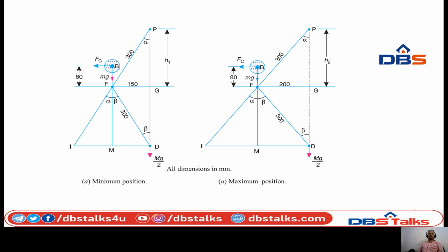Then substitute the values: FM by BM is 0.26 by 0.34, into (10 plus 100) by 10, where small m is the mass of the ball and capital M is the mass of the central load, into 895 by h1. What is h1? Height of the governor, which we just found as 0.26. So finally N1 is 170 rpm. That is the minimum speed.